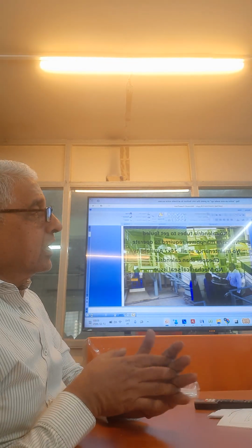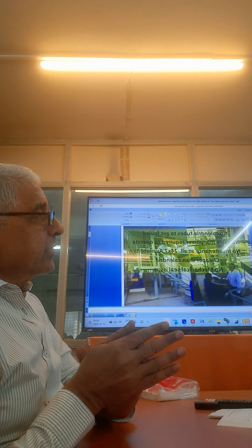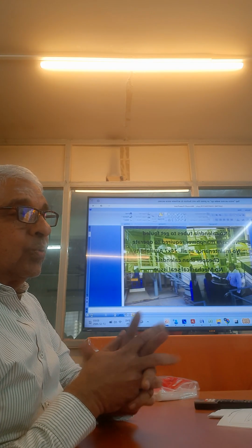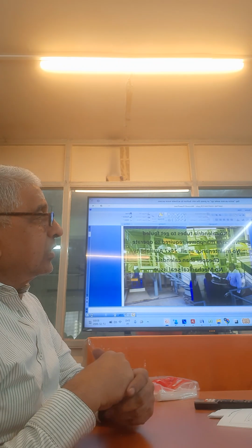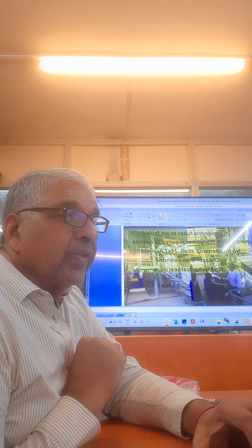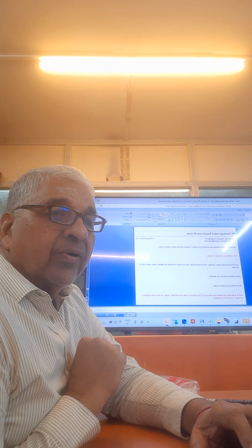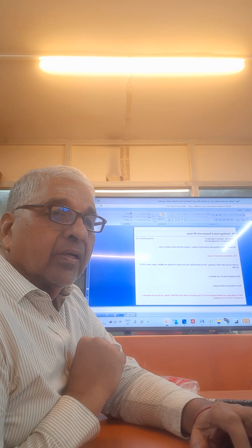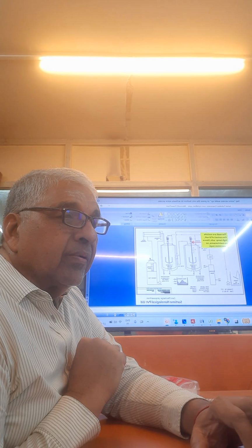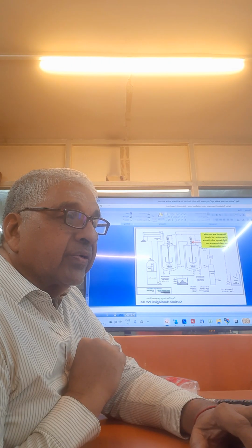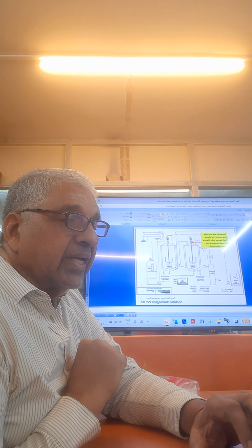What about the steam consumption? Is it the same compared to the normal one, or is it lesser? By having two vessels, that's the one I showed you before, we can have steam economy which is same as the Calandria type. The steam generated from one will be feeding into the other. See, this is the steam feeding into this second vessel.